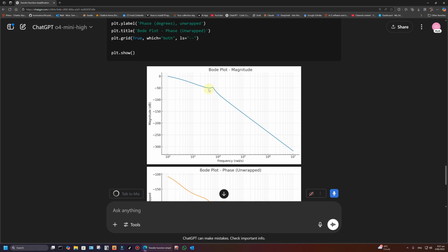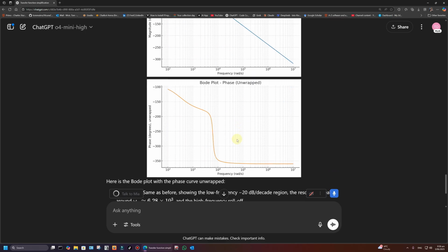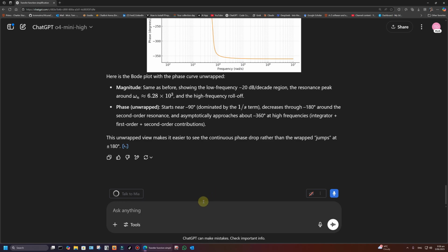Actually, maybe I should illustrate that first. So, okay, I'll illustrate that first to show that that's the case. Maybe I should say increase the forward path gain by 50 dB, and then that'll show you, and then simulate the system using negative feedback. Let's just do that as an example, just to show you that doesn't work.